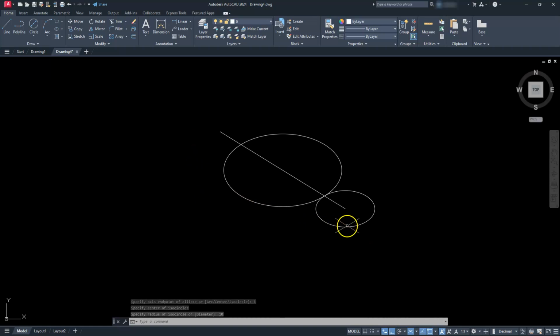So we can go ahead and copy this circle. I'll use grip since that'll make it faster. Go ahead and select your ISO circle. Select the center grip. Select the word copy on your command line here. And then pick that endpoint there.